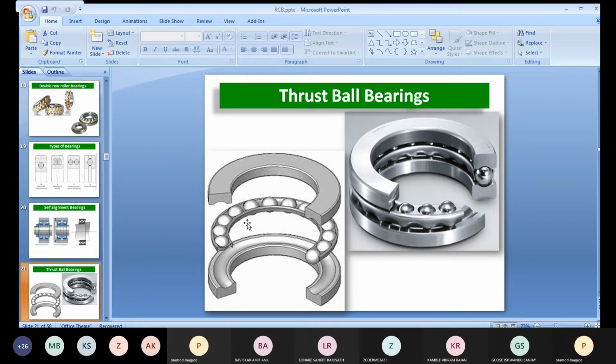Okay, generally what happens, thrust load will be taken maximum by roller bearing. But using a roller every time means the manufacturing cost goes higher. So instead of that, many automobile industries use ball bearings, but from an angular point of view. Though it has more maintenance cost, it will perform in the maximum sustained condition for thrust load. So likewise, it can be used.